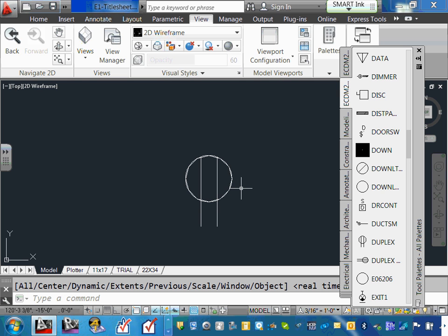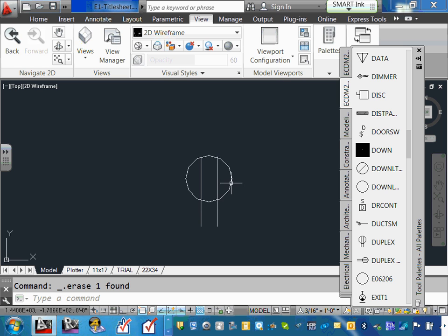Okay, were you able to drop the receptacle? Okay, now after you drop it, why don't you click on it and delete it, will you? So you don't cause a problem. Delete it. But that's how you drop your receptacles from the tool palette when you have the background. Can I have thumbs up, Chad? All your symbols are here. If your symbol is not here, then we have to create it and bring it up.